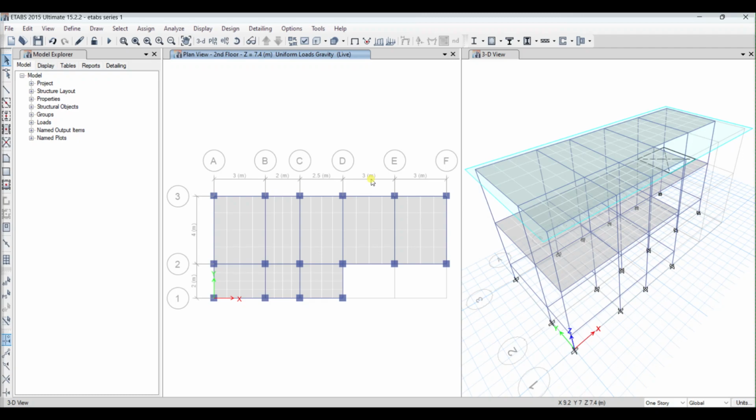is of two types, live load and dead load, and we have the wall loads on the frame, like partition walls. We can consider a partition wall as a dead load on the floor, and this will be in terms of force per unit area, which we can call force intensity, and the other is force per running meter, like wall loads for the frame structure.